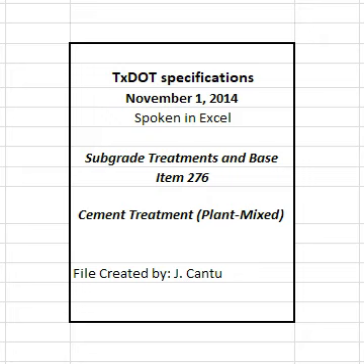4.5 Microcracking. Maintain moisture content of the finished cement-treated base for a period of 24 to 48 hours when shown on the plans. Roll the finished course with a vibratory roller to induce microcracking during this time, but not sooner than 24 hours. The vibratory roller must be in accordance with Item 210, Rolling, with a static weight equal to or more than 12 tons and the vibratory drum must be not less than 20 inches wide.